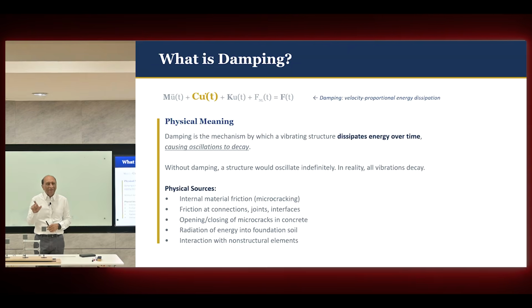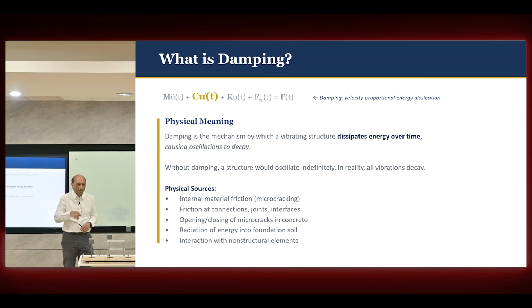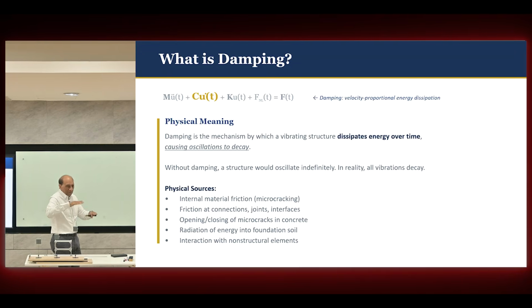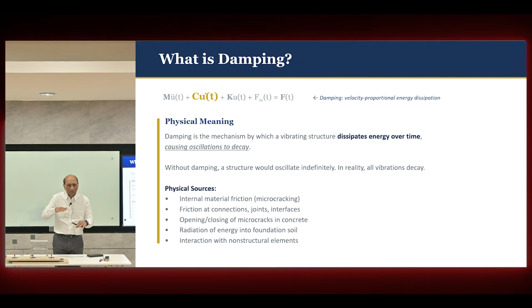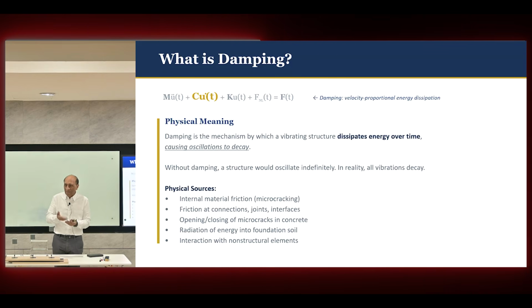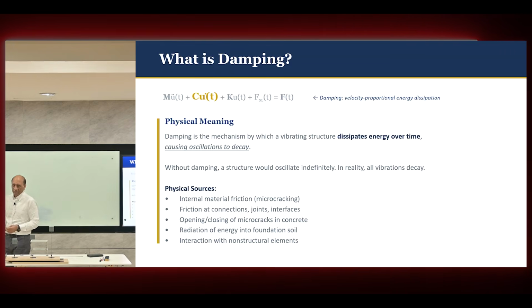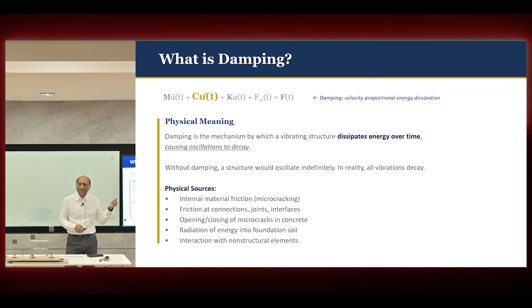That's pure damping attached to a moving vehicle, because the ground is varying and there is a mass, so there's an acceleration it's going to damp. Otherwise, you will be jumping around too much on the motorcycle. To make your ride smooth, that energy coming from the road because of your mass moving up and down is all being absorbed by that damper. Now so many kinds of dampers are there, but that is exactly what this is.